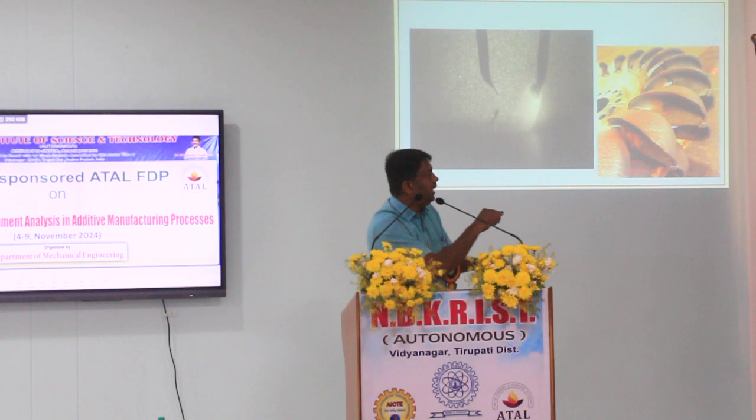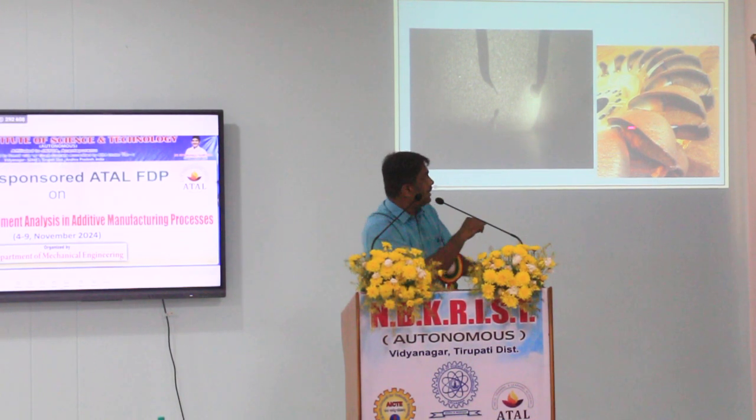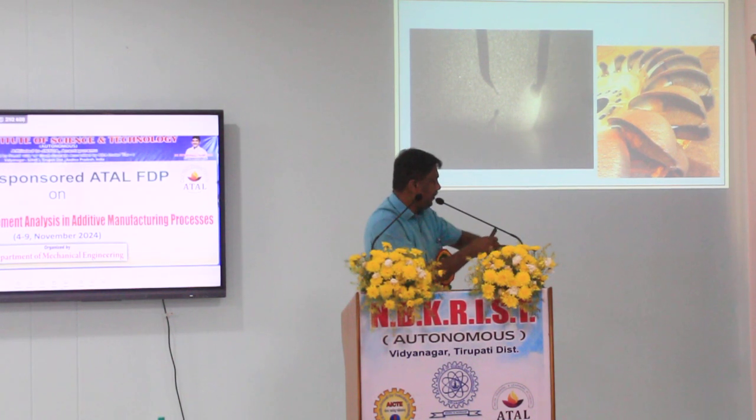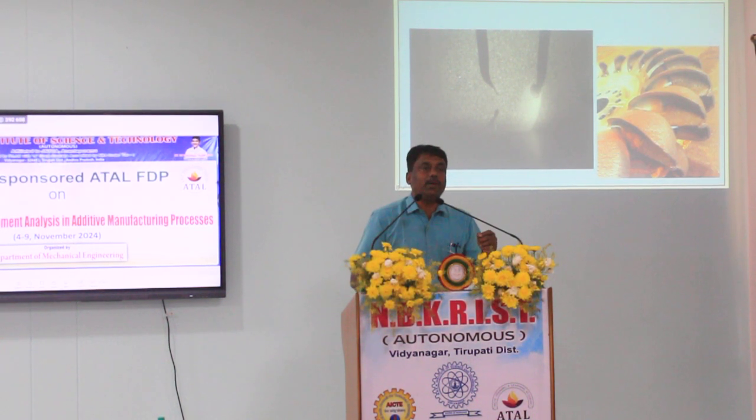And this part we make with nickel-based alloys so that corrosion resistance is achieved. Suppose you want to use a welding-based system, right? We can start with the conventional high-strength steel shaft and then start depositing nickel-based superalloy on top of it. During this process, we can also vary the composition very smoothly.